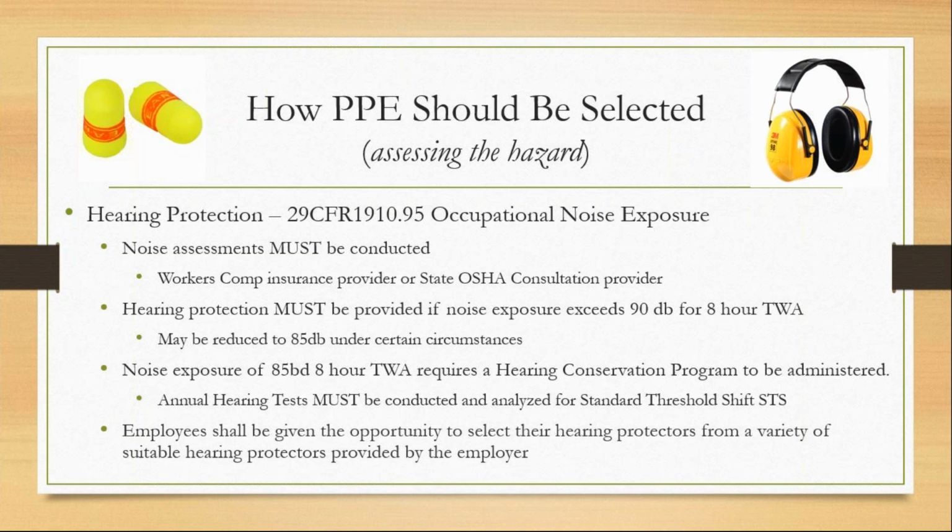Okay, so you always have to conduct a noise assessment, which is personal monitoring, where the people walk around with the little device hanging on their belt and the little microphone that clips on their shirt up near their ear, and it measures how much noise they're exposed to. And then an industrial hygienist takes that data and tells you this is what the 8-hour average is that those people are being exposed to. That's just the way that it has to be done.